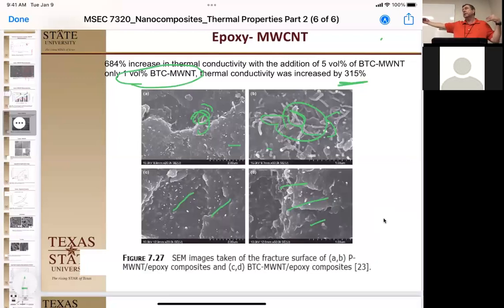The longer a persistence length you get with your nanomaterial, and the fewer of those interfaces, the better. Or you improve the thermal conductivity of the interface. If you improve the thermal conductivity of the interface, you actually have less resistance to go from matrix to filler, matrix to filler, matrix to filler. Okay. So that's what I think they're doing here is they've got a much better interface between the matrix and the filler. They've decreased that thermal resistance.